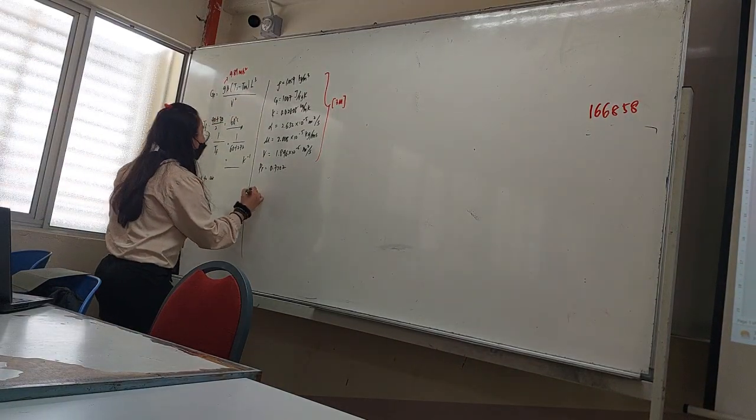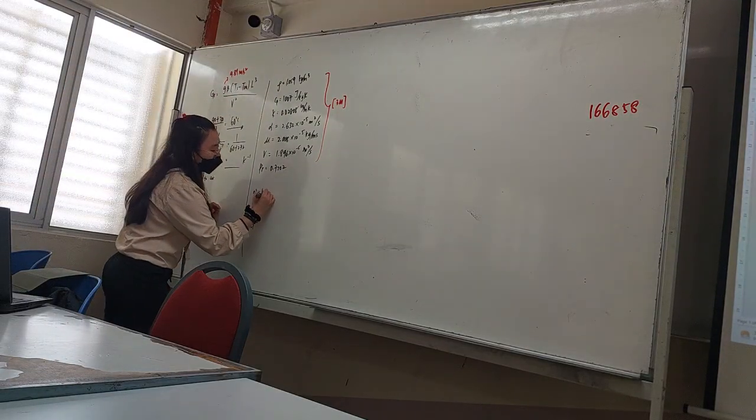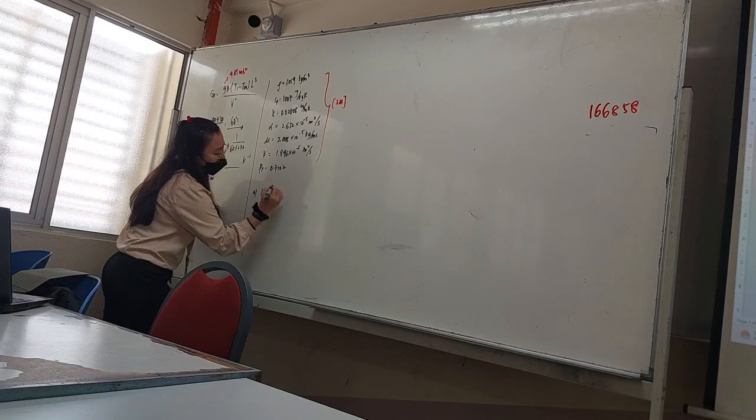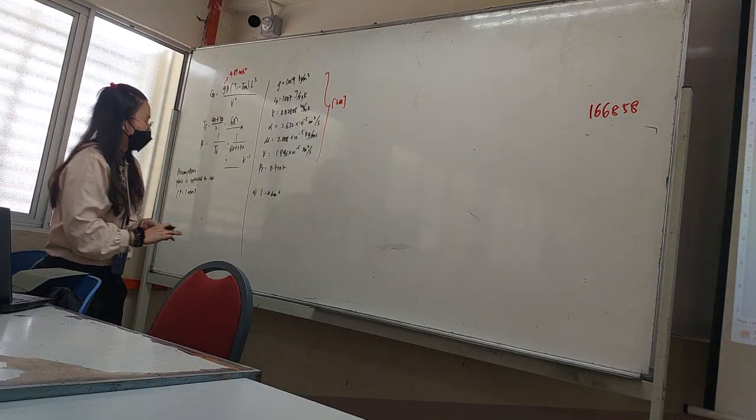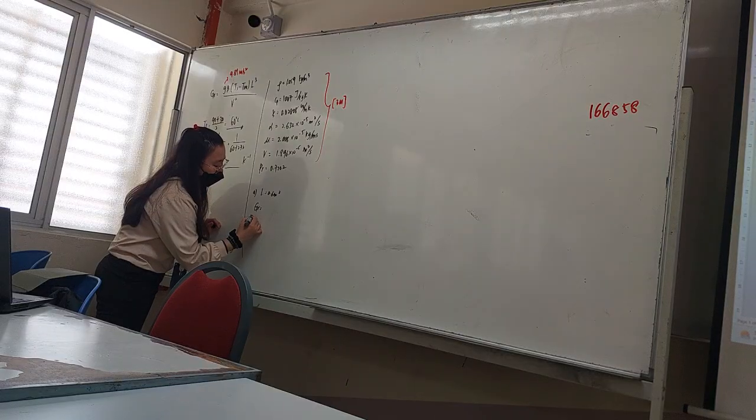Okay, so you just step inside. Your L value is equal to 0.6 meter. Okay, so you can calculate your Grashof number. Then you can calculate the Rayleigh number, which equals the Grashof number multiplied by the Prandtl number.